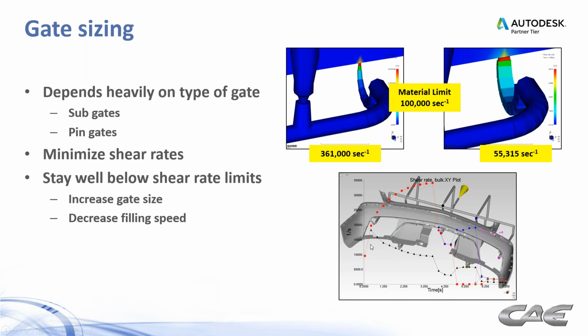And you can see we have the ability to track the shear rate throughout the cycle. And I put this one up here to illustrate what happens in a valve gate sequence situation. The first gate to fire is the one that sees all the flow coming through one gate. So you see it's the one that shows the most amount of shear. And then the ones, as they turn on in succession, start to share the flow, and all the shear rates tend to come down from there.